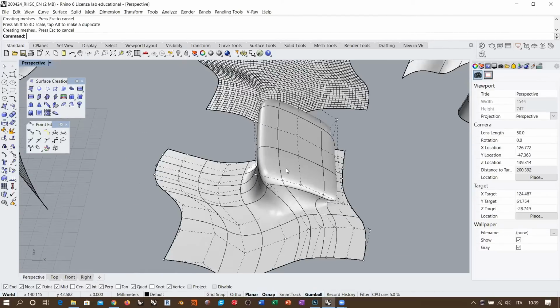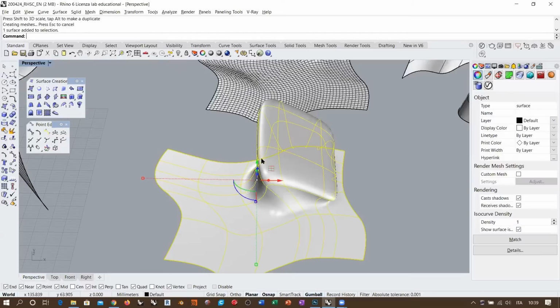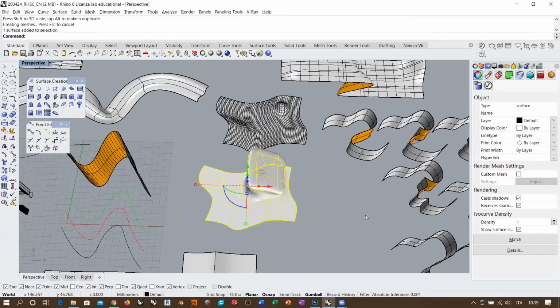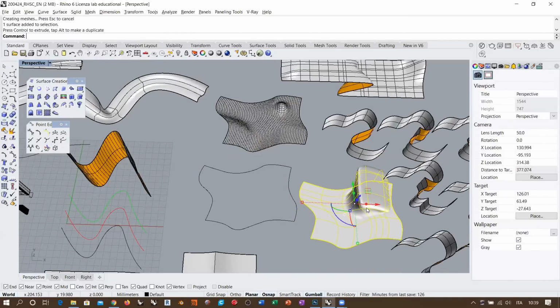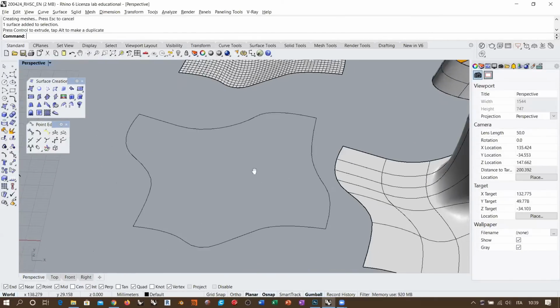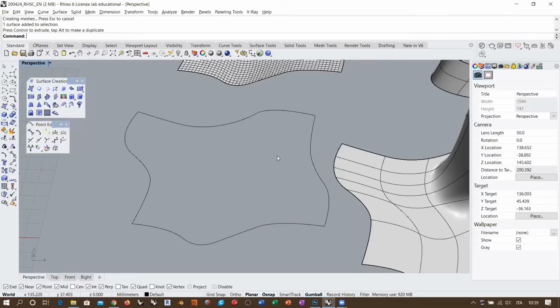And you might think, okay, without considering this extreme situation where I made this extreme edit, if I try to create a bulge in this area with this command, the surface from network curve, what would I need? Well, I would need internal curves. Internal curves basically become internal knot lines for our surface. So the surface is forced to pass through the internal curves.